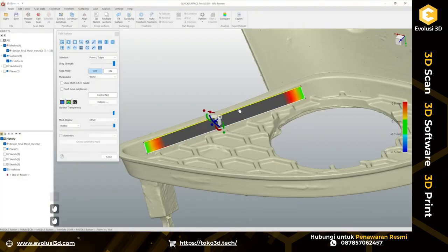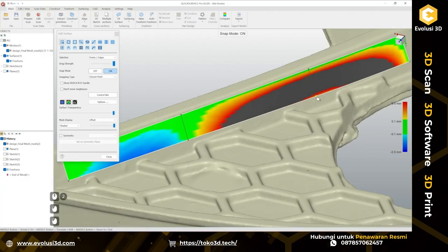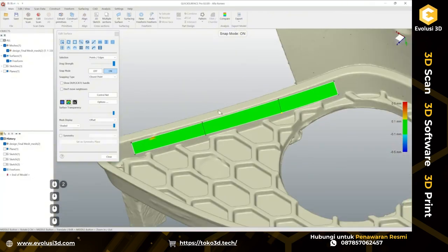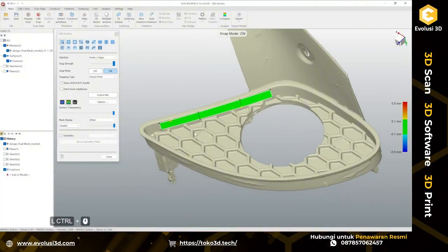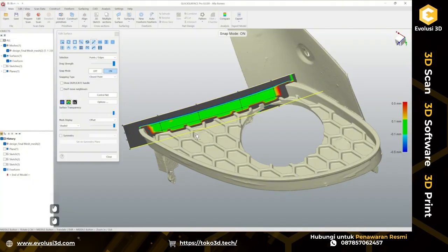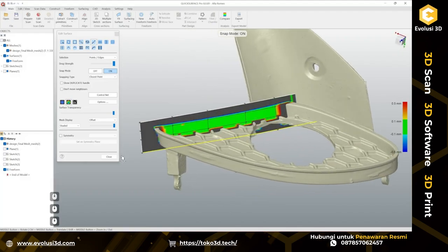So let's fit freeform. Let's subdivide it a couple times. Okay, so we're super great at deviation here at the moment. And of course we could go patch by patch all around this part, or probably a more advanced way would be to simply extend this surface, say in all directions, so it completely goes through all my scan data.